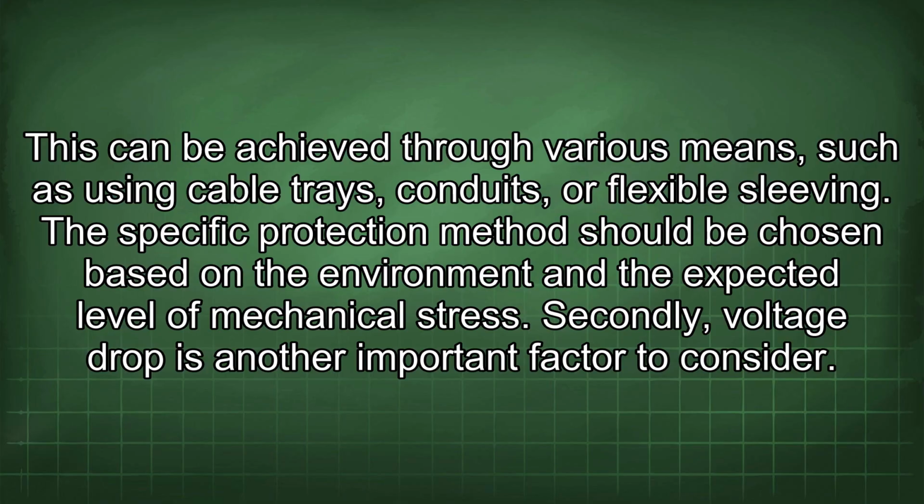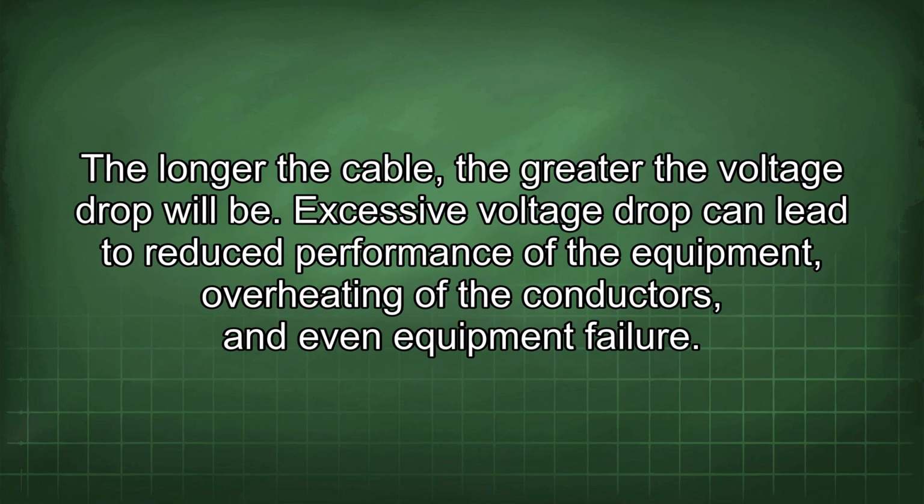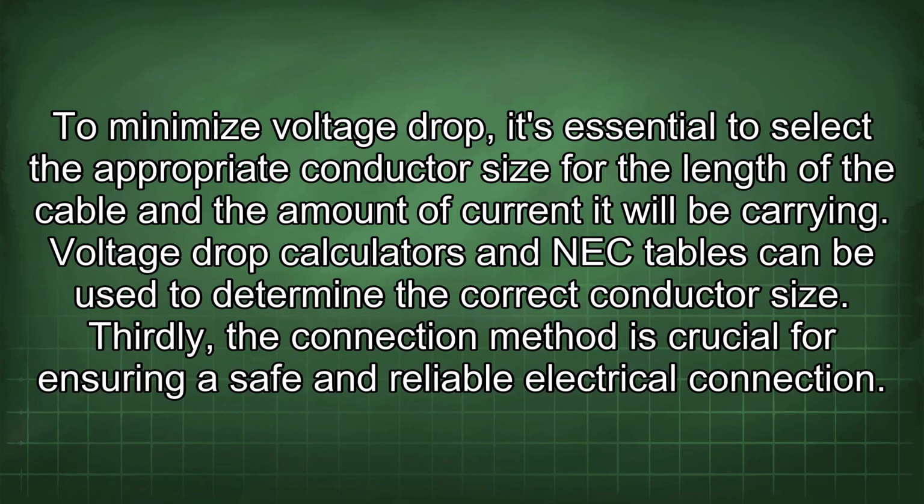Secondly, voltage drop is another important factor to consider. The longer the cable, the greater the voltage drop will be. Excessive voltage drop can lead to reduced performance of the equipment, overheating of the conductors, and even equipment failure. To minimize voltage drop, it's essential to select the appropriate conductor size for the length of the cable and the amount of current it will be carrying. Voltage drop calculators and NEC tables can be used to determine the correct conductor size.